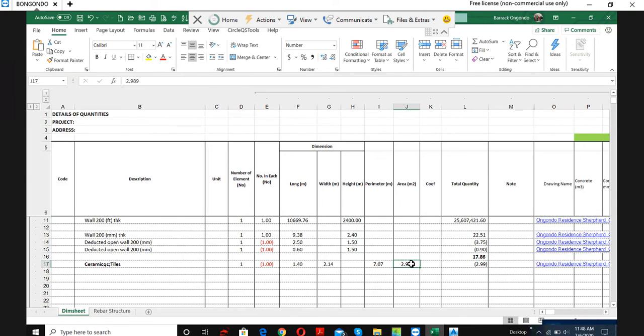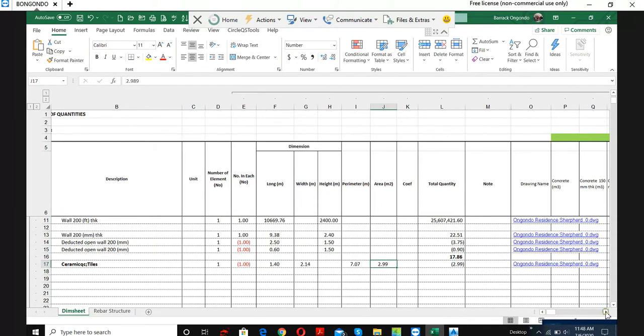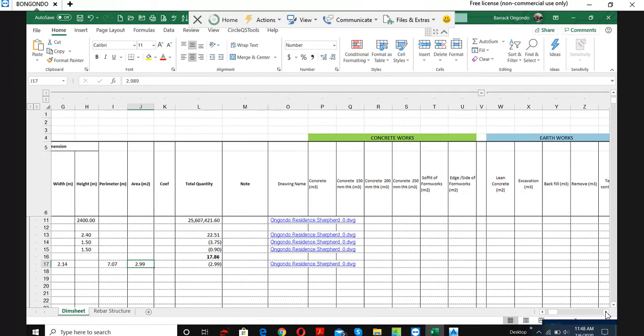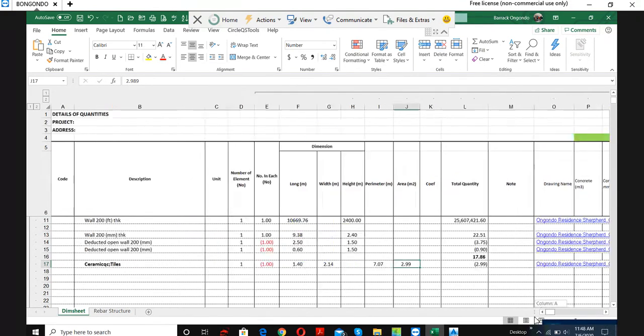So maybe if you want to do things to do with cornices, cutting, which means you're going to use the perimeter. And when you come this side, now this exported just the area. This option wasn't for concrete works, for slab works. If it was slab, even if this one is an opening, it would have deducted from the area of the wall slab. Then it knows the area of the opening, it deducts it from the area of the slab.